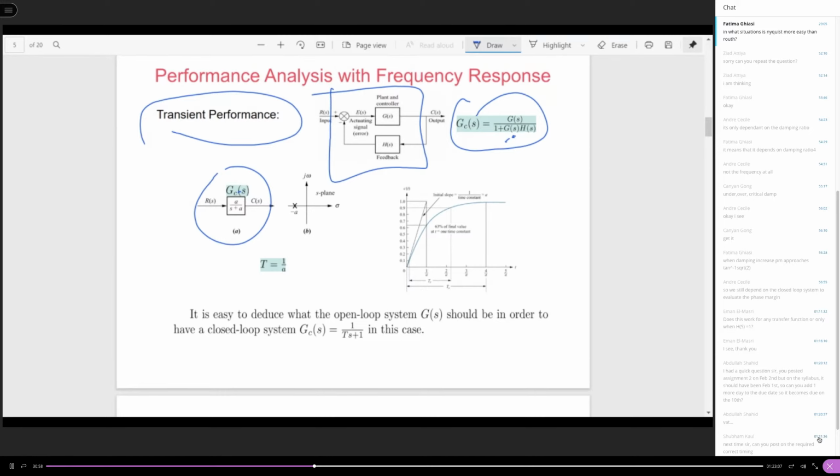And before you move to the control design, the reason that you evaluate your plant's performance is just to find out the deficiency between the plant system itself and the target closed loop, controlled system. Once you can identify the deficiency, then you will be able to find the appropriate controller to be added in here to make sure the closed loop system satisfies your performance requirement. So in this sense, the performance requirement is always posed on the closed loop system.